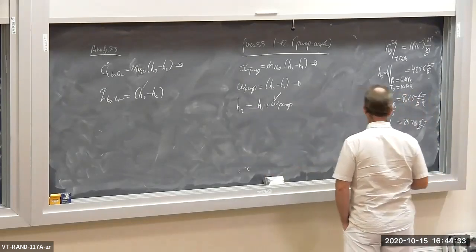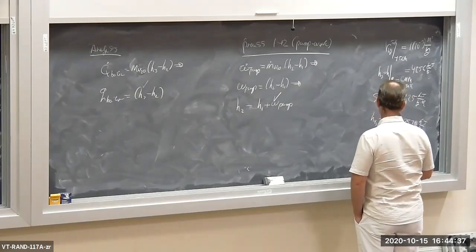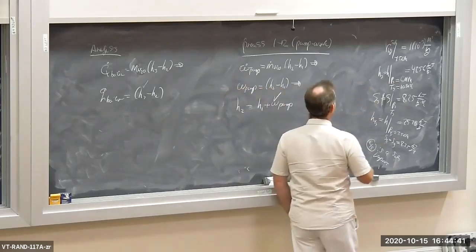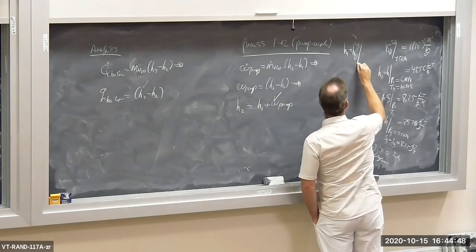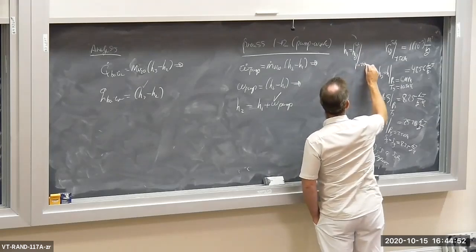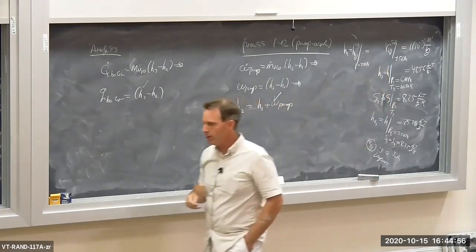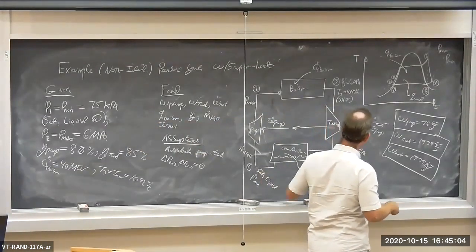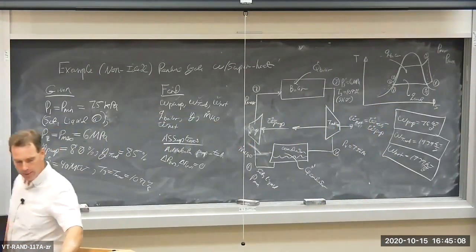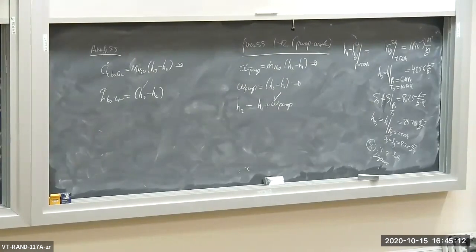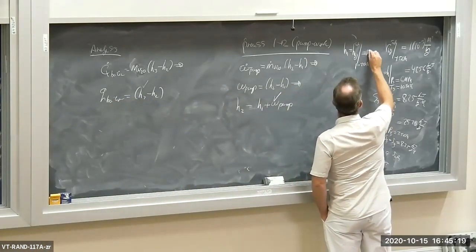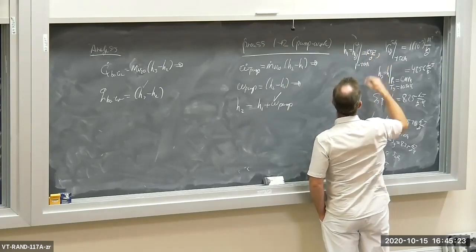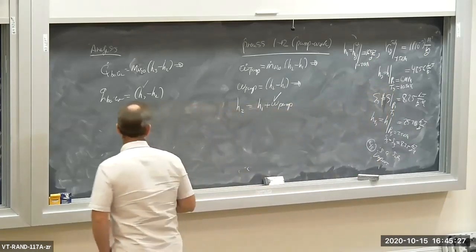So H1 equals h of the saturated liquid evaluated at a pressure of 7.5 kilopascals. State 1 is a saturated liquid. That's pretty easy to do. I can look it up in a saturation table. And I find H1 is equal to 168, it's actually 169 kilojoules per kilogram. That's from a table, interpolated from a table. Okay, now I have H1.